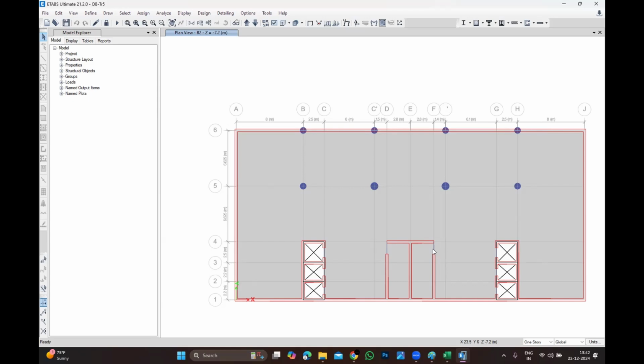The base of the structure is from ground level. Sometimes even the ground floor is half buried, because of ground undulation and topography. Maybe 1 meter is buried and only 2 meters is above, then you need to go only 2 meters. You should not take anything which is buried below ground. Cantilever.